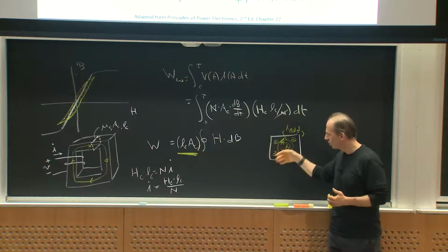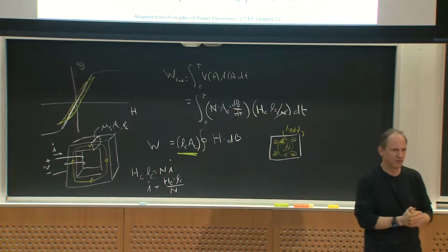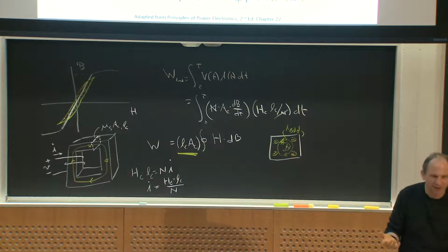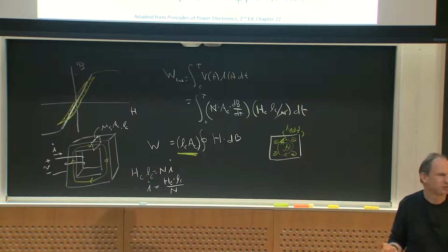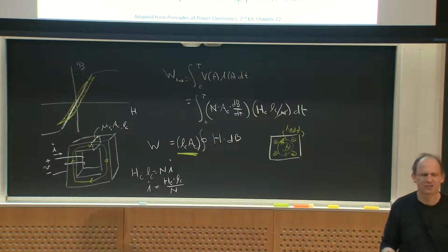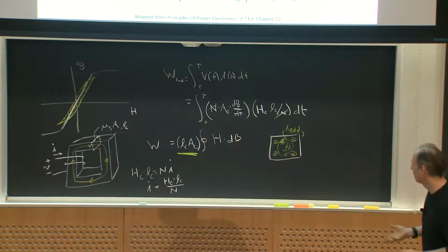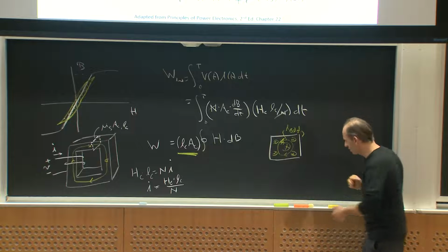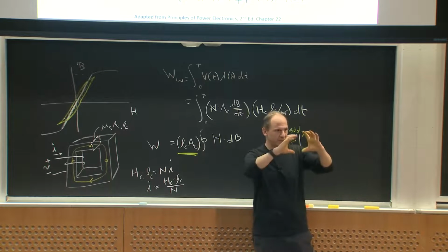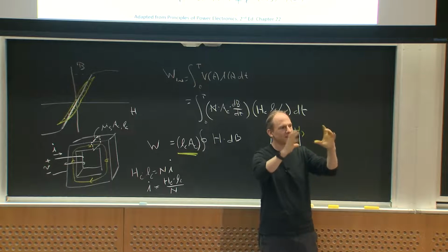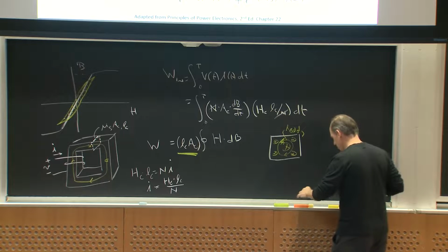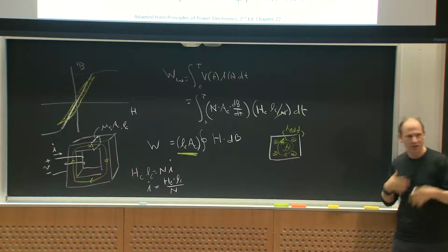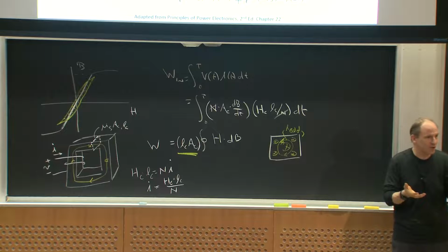Right? So what do people do about this? If you have high frequency materials like ferrite, it turns out they're not very conductive. Okay, so you don't usually worry about eddy currents in your loss in your core unless you're at really high frequencies. But if you're at low frequency materials like steels, you do have to worry about this. How do they fix this? Instead of making one big giant core cross-sectional area, they sort of take the same trick. What they do, they don't need to Litz transpose it because it's not like they're carrying current in it.